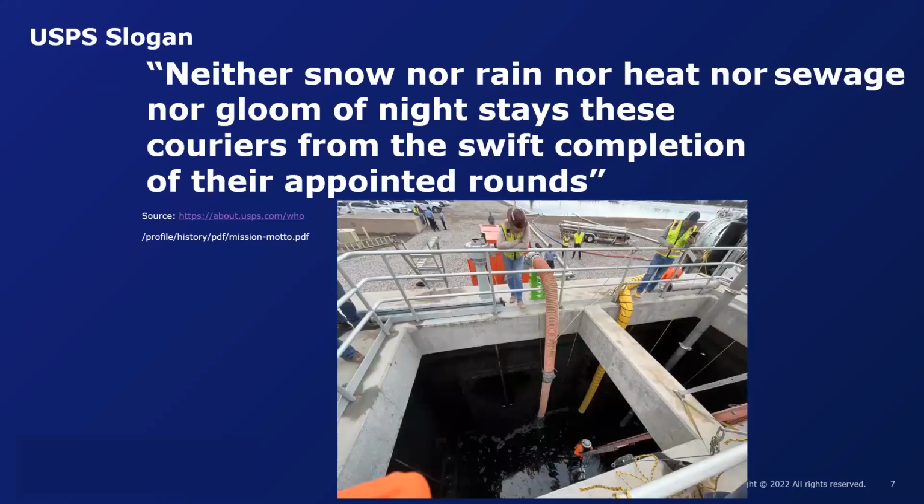And this is a picture of the secondary effluent structure over at the Clark County water sewage plant on the other side of town. And I've circled it here. You can kind of tell, but down there is that very Leica P40 system down in the sewer line. Luckily, only the tripod got wet, and we Clorox wiped it and everything. Randy Norton is down there, and Tom and Colton are up top making sure everything's safe. But they needed to scan to measure the wall-to-wall dimension to install a bulkhead.